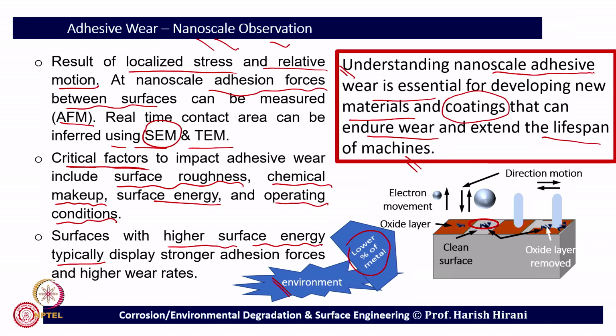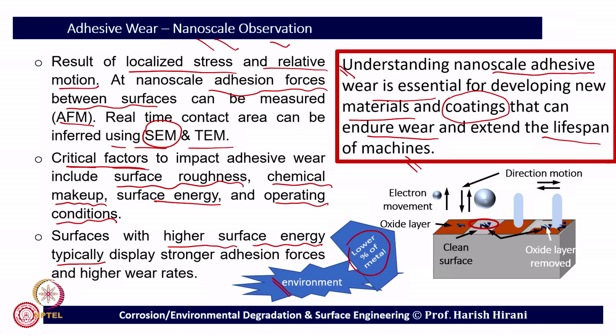First, it is a weaker surface. The oxide is going to make a weaker interface. So, a weaker interface is essential, and in addition, the material which is getting transferred or will be lost is also lesser. So, that is very important. If you are able to form the oxide layer on the surface, it will be very advantageous. Or if we can make the surface chemically inactive, that will also be important for us.